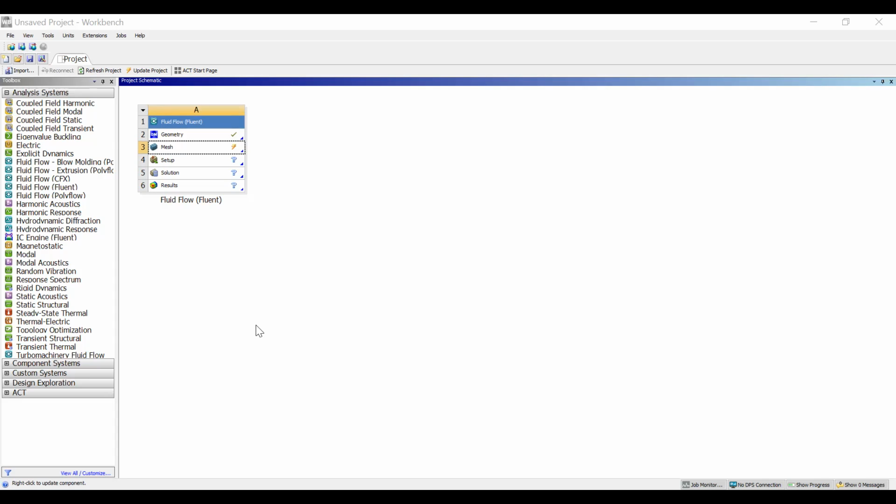And then we're going to change under inflation option. We're going to look at first layer thickness is what we want to define. And we're going to define that as 0.02. We will do 100 for our max layers and a growth rate of 2.5. Okay. And then let's go ahead and generate that. This will take a second. As we're adding some of these elements and starting to refine our mesh size, it's going to take us a little longer to load.